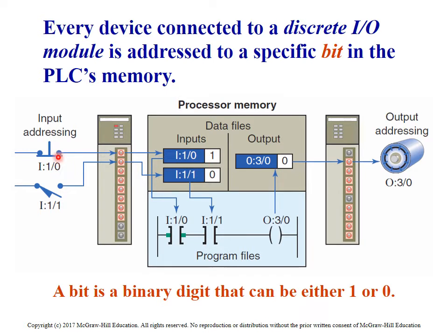When that state does turn on, as you can see, it turns to a 1, and it highlights that contact as being closed. This guy here is an open state, which is slot 1, bit 1. That's off, so it means it's open, so you will see this not highlighted. Because that's not highlighted, this is not highlighted, that output is off.